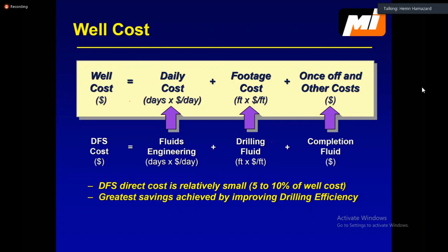Okay. Somebody yesterday asked that question, the challenges we are facing while drilling in HKN blocks. One of them is preventing shale from collapsing. We've had issues in the past and we've been stuck and we've lost millions of dollars because of the shale swelling and collapsing. So we are using KCl as one of the shale inhibitors. KCl is a kind of salt. Also, we are using PHPA material, and also what they call DrillTex, IBTex. About 5 agents we have in our system to prevent the shale.